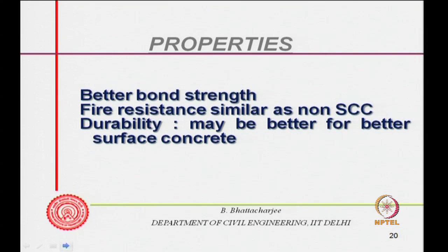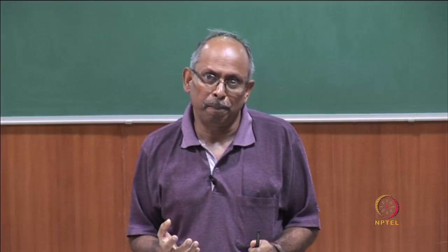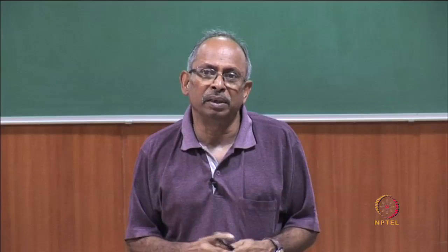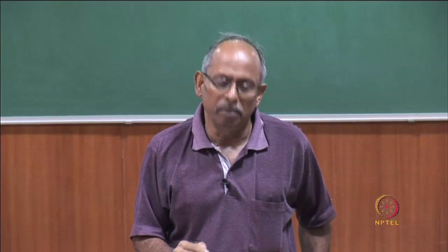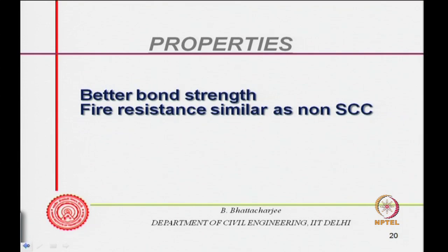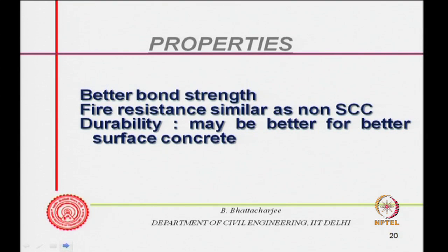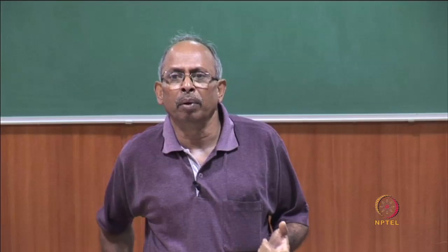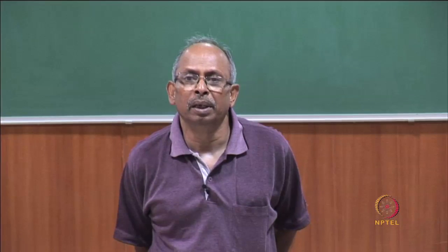Since surface may be better, because we have seen durability is related to surface concrete, all right, near surface concrete, and therefore, this may be slightly better. So, no significant difference with the non self compacting concrete in the properties concerned.